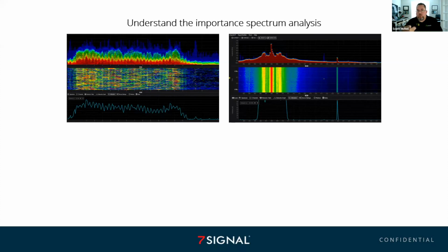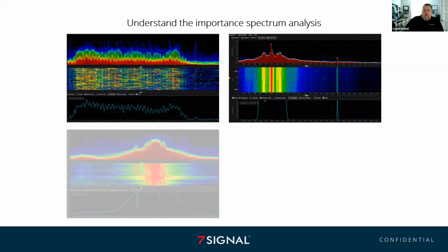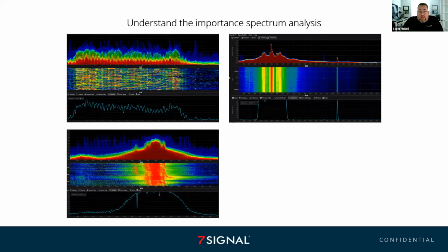So I was able to generate a pretty high-powered signal in the ISM bands for 900 megahertz, because I just wanted to see what it was looking like, but I could also use it for penetration testing to know how far 900 megahertz is going to be able to penetrate through, say, walls or this band of piping or whatever. But now that I know what that signature looks like, if I see that signature out in the wild, then I'll know that someone else is using some kind of signal generation and/or jamming technique, because this is one of the several signatures that will key you in on that.